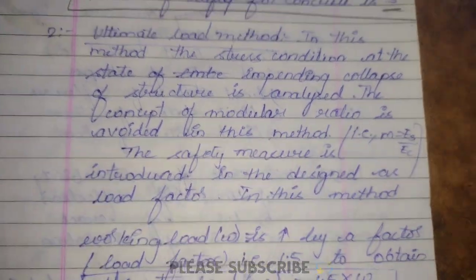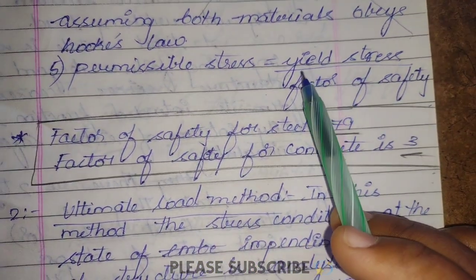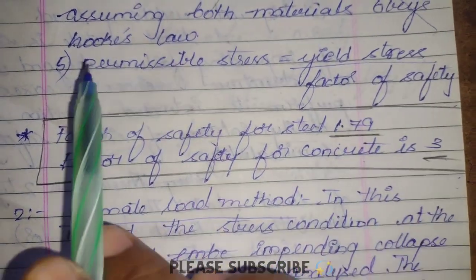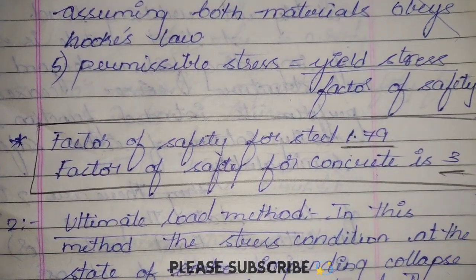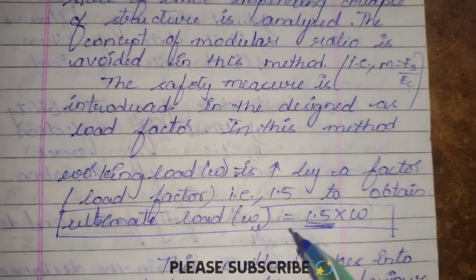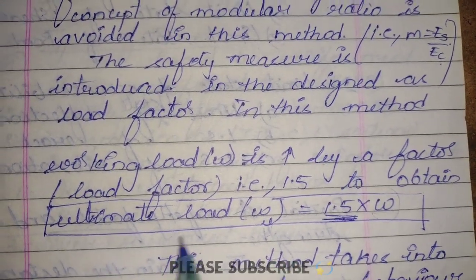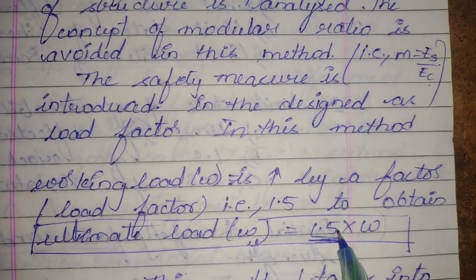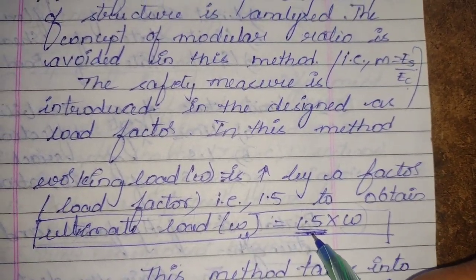In the working stress method, we had permissible stresses, where we divide the yield stress by the factor of safety to get the permissible stress, and the factors of safety for steel and concrete are provided. Now, in this ultimate load method, we develop the relation between the ultimate load and the working load. To get the ultimate load, we multiply the working load by 1.5. This is the load factor.